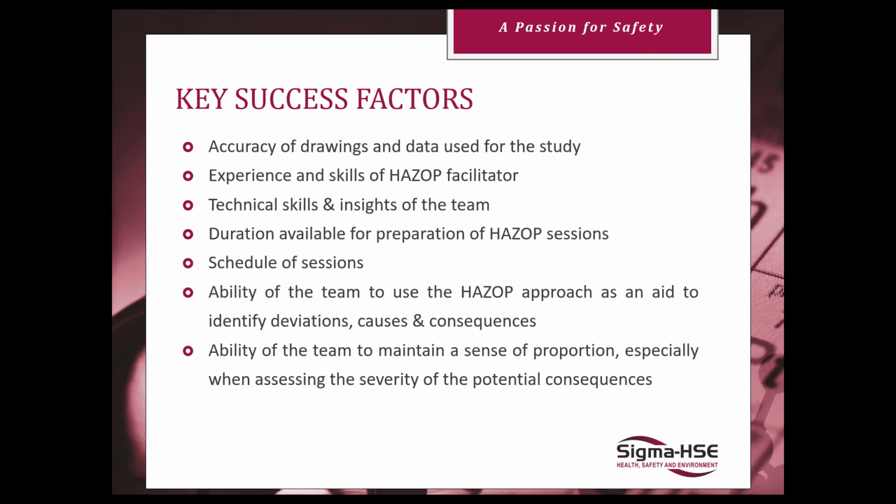Technical skills and insights of the team. If you have a brand new operator that just started a week ago, they're not going to be able to give you as much insight into the process as someone that's been working the process for an extended period of time. Duration available for preparation of the HAZOP sessions. You want to make sure you give adequate time for the nodes to be developed and the PSI to be reviewed prior to walking through your HAZOP.